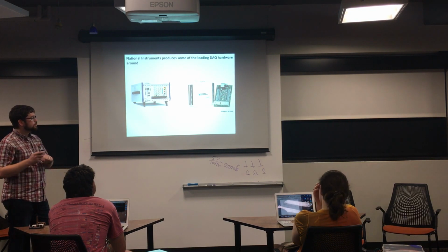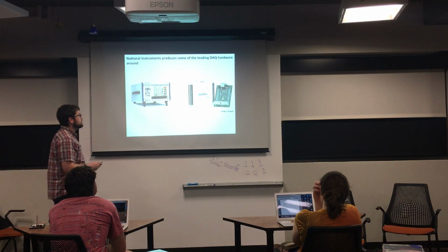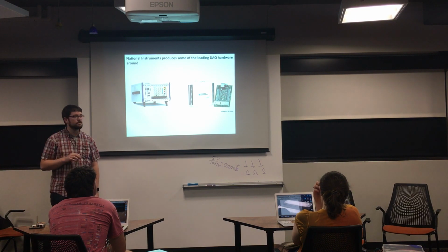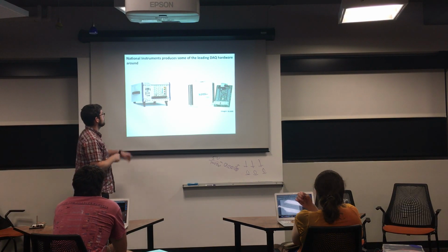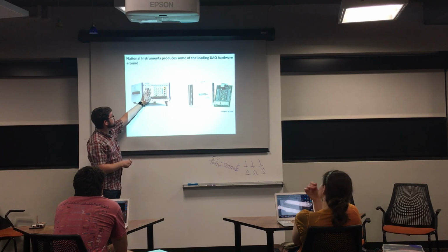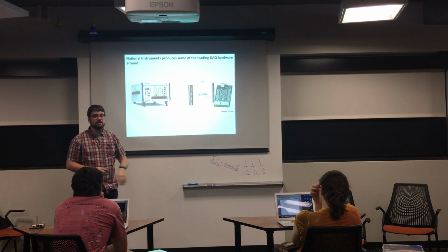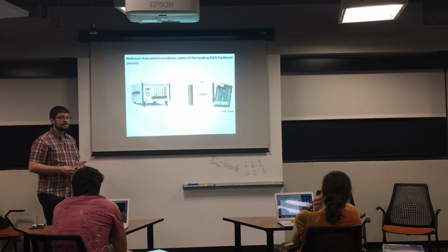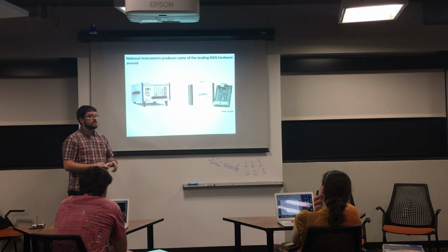Alright, so I'm going to show you some of the hardware that's available, places that you should go look if you need to do data acquisition. I would say that National Instruments is probably one of the leading data acquisition device providers, probably in all of academia, and they make fantastic equipment. This is the PXI chassis. So here we've actually got a full computer, like a Windows computer sitting here, and you've got all these cards that you can plug in to do different kinds of data acquisition. They have some that are specifically designed for temperature, some that are specifically designed for strain gauges, things that make you have to do less externally.